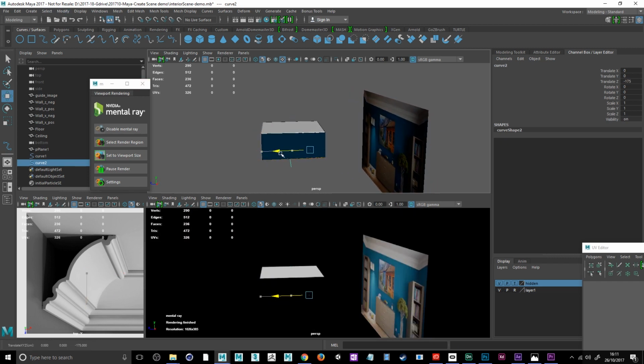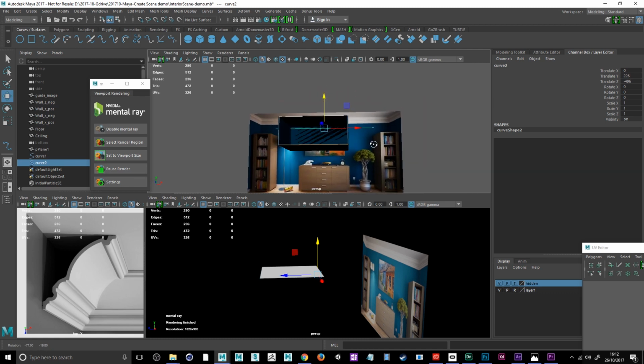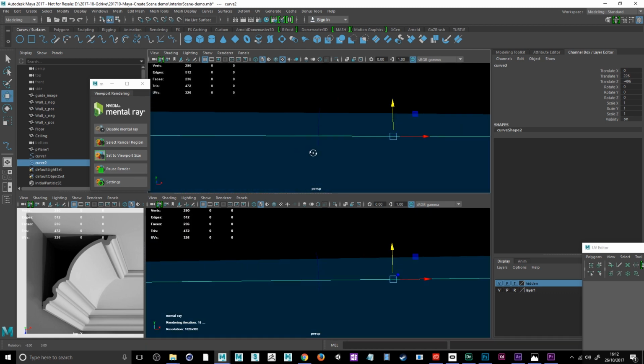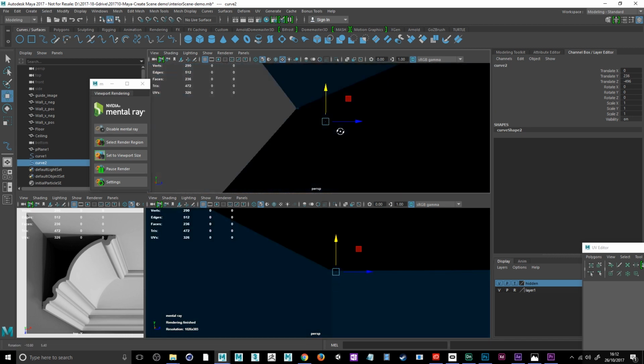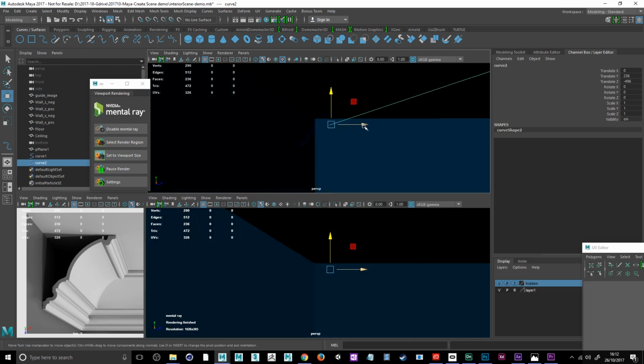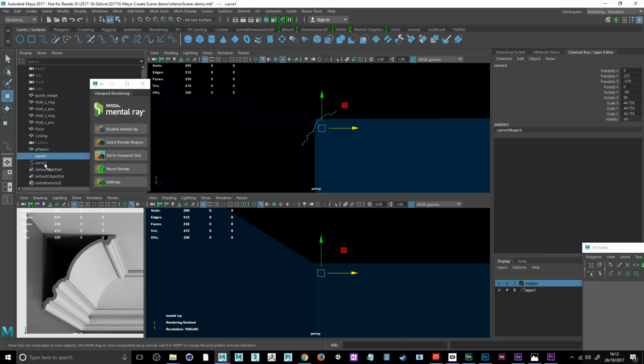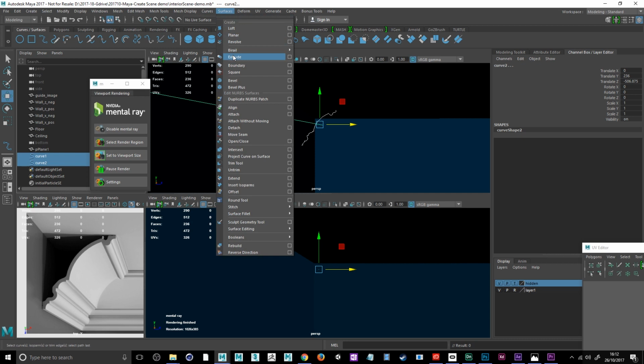Now I can see that there's a slight off centering for the center pivot on that, so I'm going to modify center pivot and bring it onto the center of the object itself and bring it round so it's inside and near the profile that I want to extrude along. Now I'm not sure that it makes a huge difference where it is exactly. You may find it does, but I'm just going to line it up and then select the first curve, which is the profile, shift click in this window here, or you can do it in the viewport, but I find it easier here, to select the line it's going to extrude along. And from the modeling menu set, I'm going to go to surfaces, extrude.